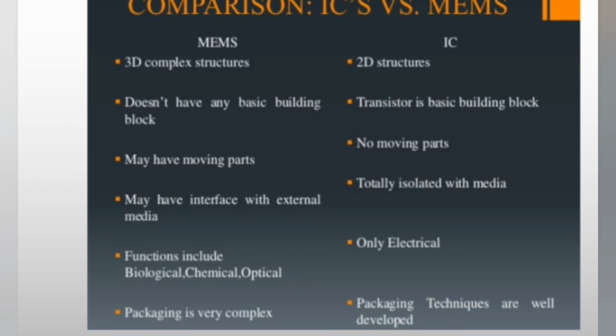MEMS may have interface with external media. In an IC, it is totally isolated from media. MEMS functions include biological, chemical, and optical. An IC is only electrical. And MEMS packaging is very complex, while IC packaging techniques are very well developed.